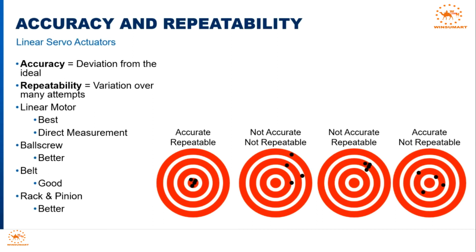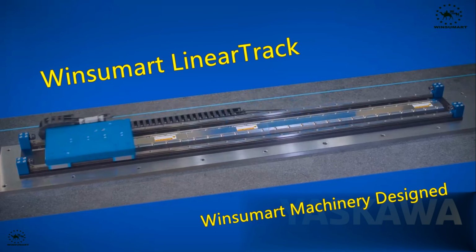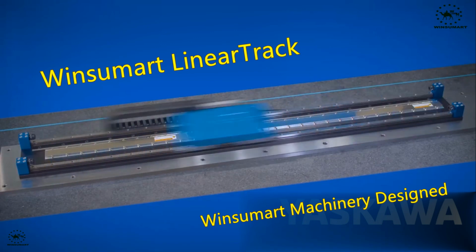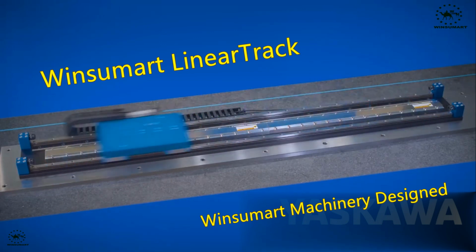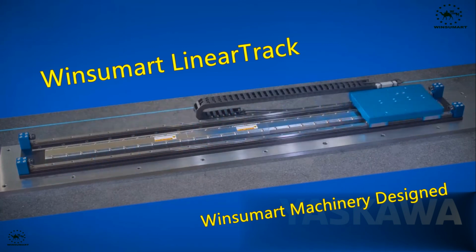The control system measures position at the encoder. Rigidity and backlash add an element of uncertainty to those measurements. Additionally, the manufacturing process of a belt, ball screw, or rack and pinion will affect the accuracy and repeatability. Only the linear motor, by natural design, measures the load directly and moves it without the backlash and compliance problems that can plague mechanical actuators.